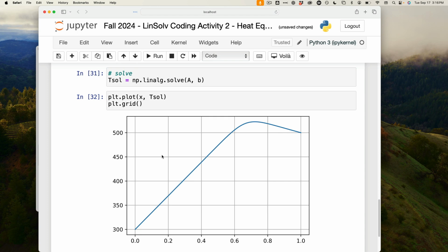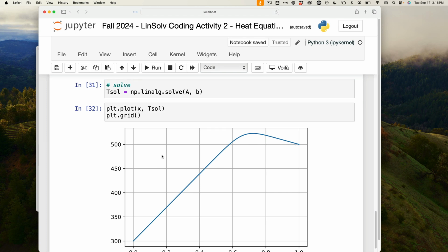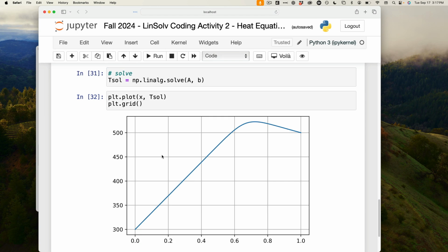Does this plot make sense? Yes or no? Okay, who says yes? So it's like counting the no's. Everyone else says it doesn't make sense. Okay, why doesn't it make sense? I want to make an assumption here, but assuming that you're putting heat onto this metal, I guess, in the middle, the temperature should increase, reach a point, and then decrease linearly.